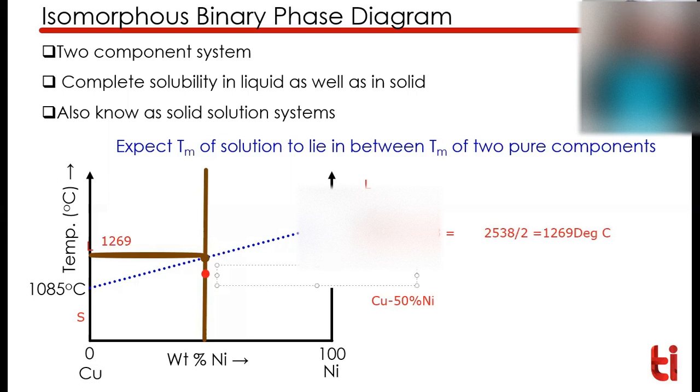So below this point it is solid, above that it is liquid, with liquefaction starting. And liquefaction doesn't change immediately. You keep on heating and ultimately liquefaction stops above this temperature, where it is completely liquid material. It means for this alloy, experimentally they observed that melting started well below this blue line and finished above that blue line. Similarly they observed it for other alloy compositions also.